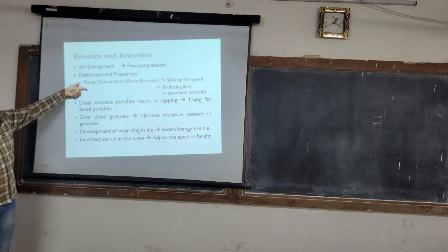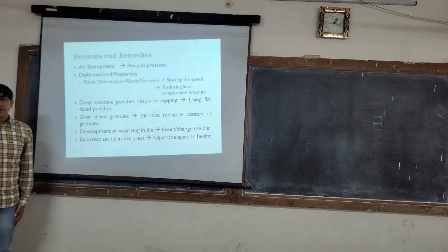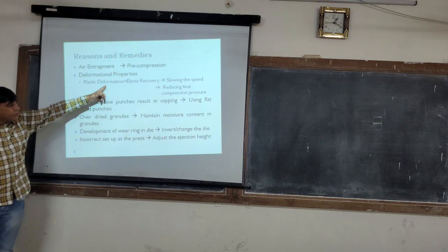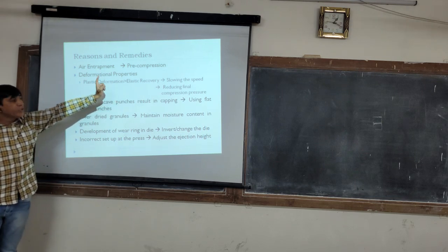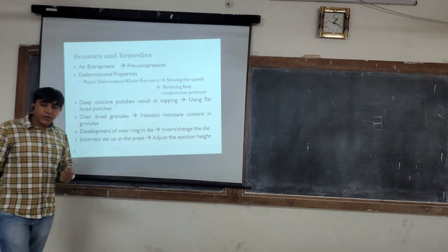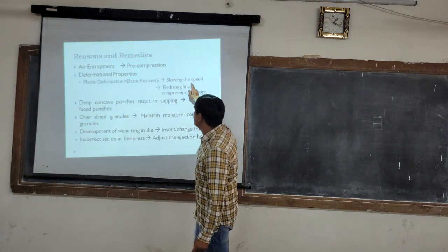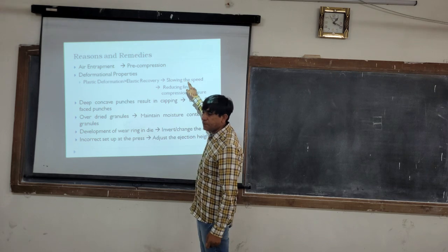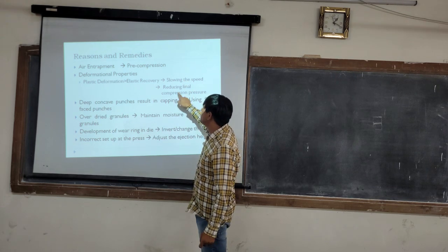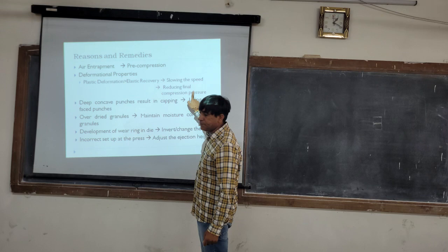Next is deformational properties. Plastic deformation is more than elastic recovery. In such a case, we can increase the dwell time. For increasing the dwell time, either we can slow the speed or we can reduce the final compression pressure.